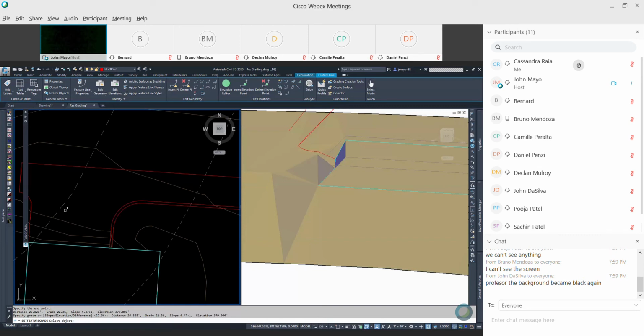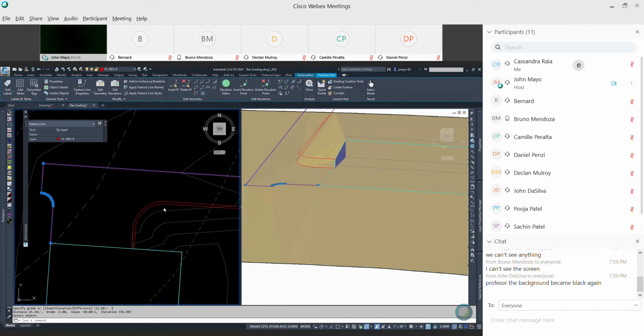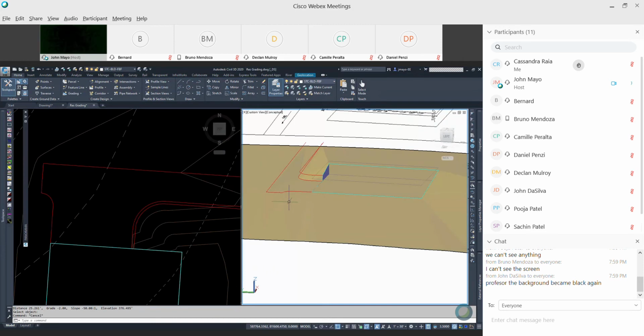Oops, I didn't get the 2% on that. Let me do that again. Grade -2, good. Down over here. Grade is -2. And I'm going to do the same for the top of the wall so I maintain that uniform 4 foot. Grade is -2. Let's hit return and see how the surface updates. Look at that. Makes a little more sense, at least for the driveway.